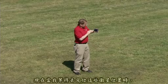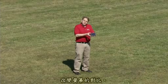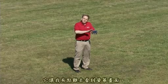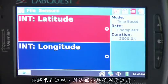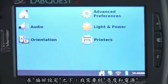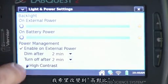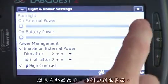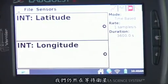Now, while I wait for this to locate the satellites, one of the things I would like to do is to change the contrast of the screen. Because we're outside on a sunny day, it can be a little bit difficult to see the screen, and so the LabQuest2 has the ability for a high contrast screen. And so I'm going to go to the little house icon, and under the preferences, I need to go to light and power, and I want to change this to high contrast. So I do the high contrast mode. You can see the colors change there a little bit. I go back, and so we're still waiting for the satellites there.